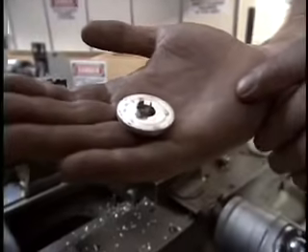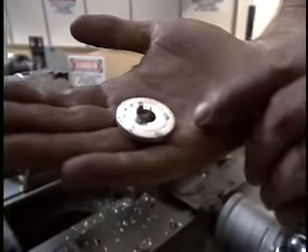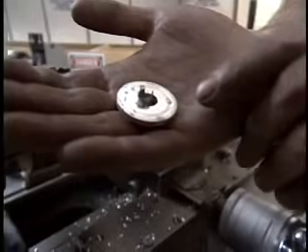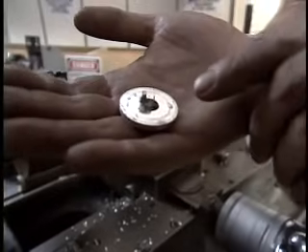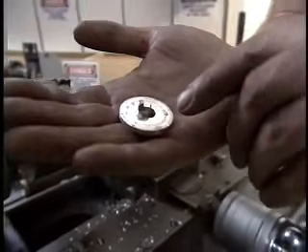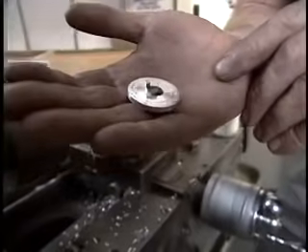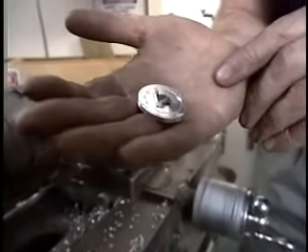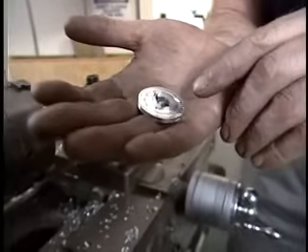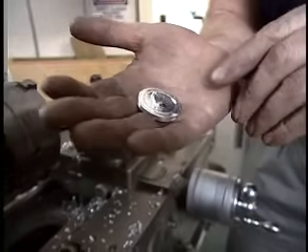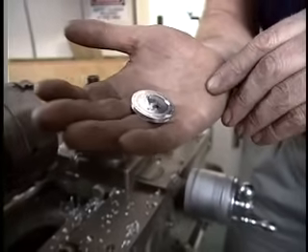You can see here the finish of the cut. About halfway down, you can see that the cut is a little rough and not as shiny. That's the part of the cut where I was not using cutting fluid. It was very clear from this the benefits of using some cutting fluid while you're using the cutoff tool.